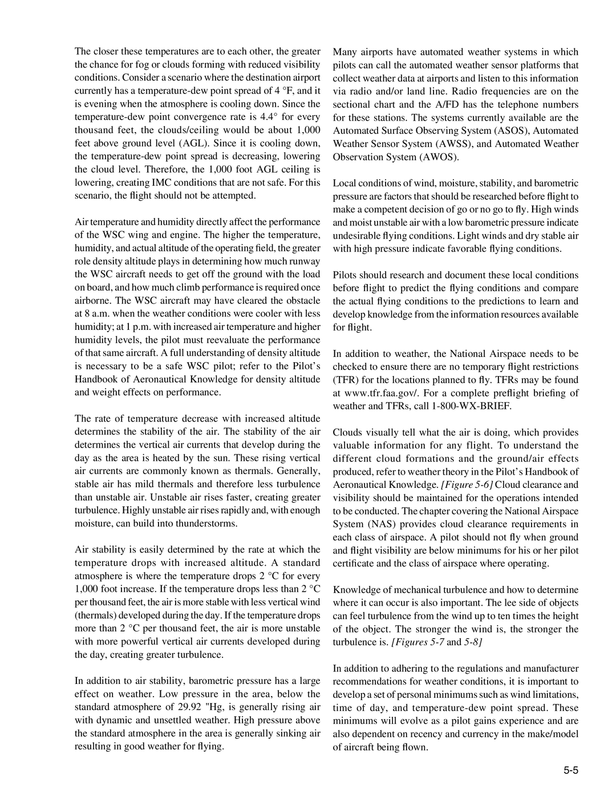Figures 5-7 and 5-8. In addition to adhering to the regulations and manufacturer recommendations for weather conditions, it is important to develop a set of personal minimums such as wind limitations, time of day, and temperature dew point spread. These minimums will evolve as a pilot gains experience and are also dependent on recency and currency in the make/model of aircraft being flown.